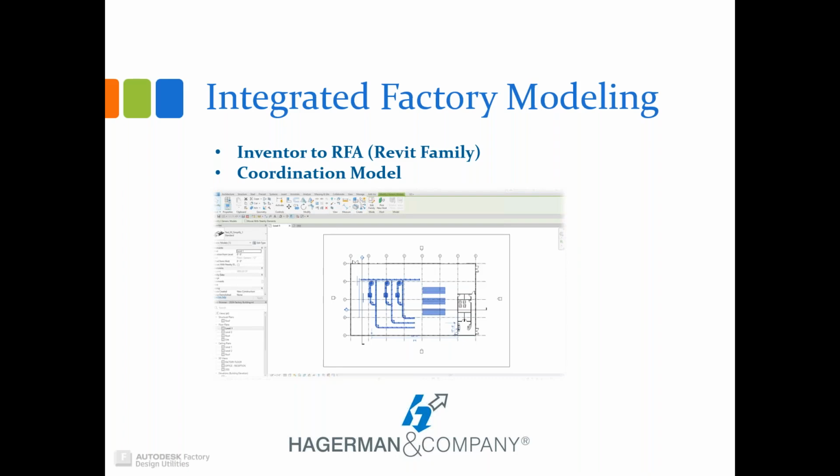You can simply load in the entire file as a Revit family. And that was what Mark was showing earlier. This is a pretty good option. Even though it was not originally authored in Revit, the RFA file is a native format and it's going to work very well. The only drawback here might be that the entire layout file could be very large in file size and could cause some issues there. I'll elaborate on that a little in our demo.